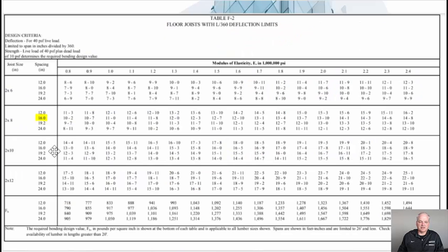As we look at this chart, our first goal was to use a 2x8. I know the print here is small, but I'll read it through for you. The joist size is in the first column here. The second one is our spacing in inches, so we're going to select 16. And then over here is the modulus of elasticity, and what we want to look at is finding a number here. See, 10 foot 2 inches the first one, 10.7, 11 foot, and it carries all the way over here with a higher modulus of elasticity, which means more bending.